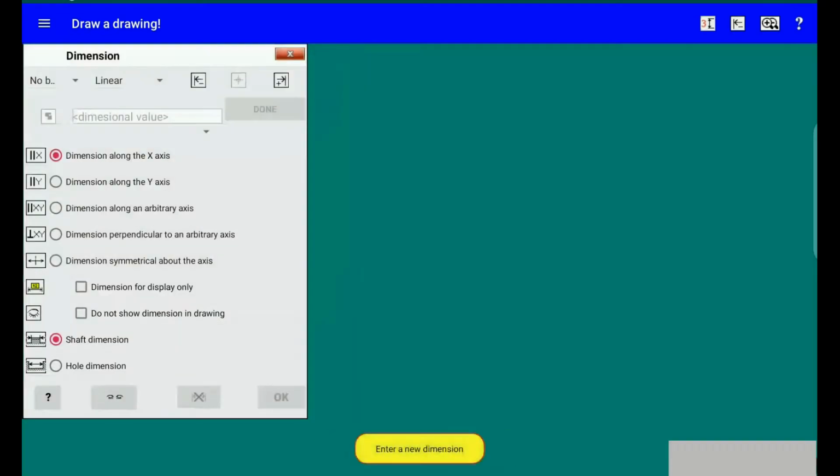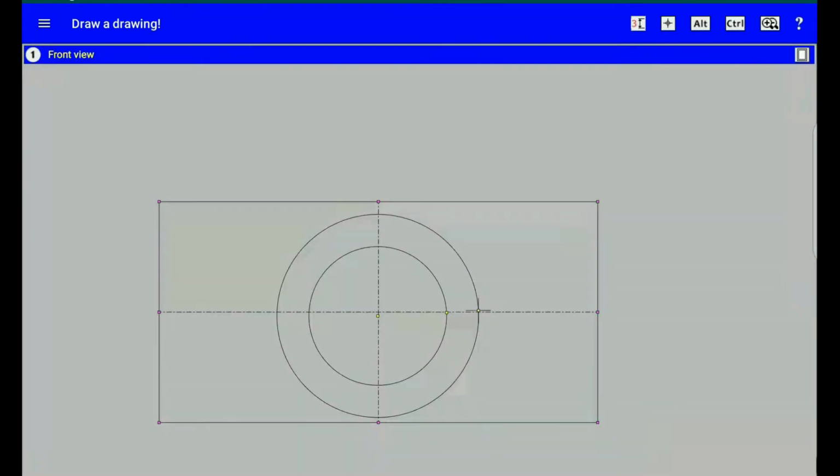Let's introduce the second dimension of the diameter for the second circle, already the dimension of the shaft. The center did not fit in there. Let's fix it now. Press the Alt button, and again we mark the same point. The center mark has disappeared. In this way, you can make changes to the arrangement of already entered dimensions. Disable the Alt key and specify the correct center point.